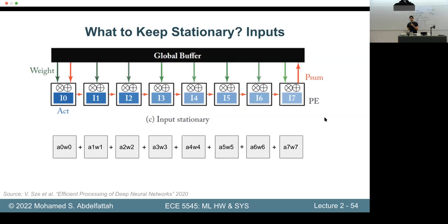Yeah, running inference on several DNNs and averaging outputs. I think that's valid. It's interesting because if you run on different deep neural networks, then we're talking about end-to-end running, and usually you can't keep the activations or the inputs cached in your PEs for that long. Usually it's on a per layer basis or even per tile basis, so a piece of a layer, connecting the layer in question into multiple tiles, potentially.